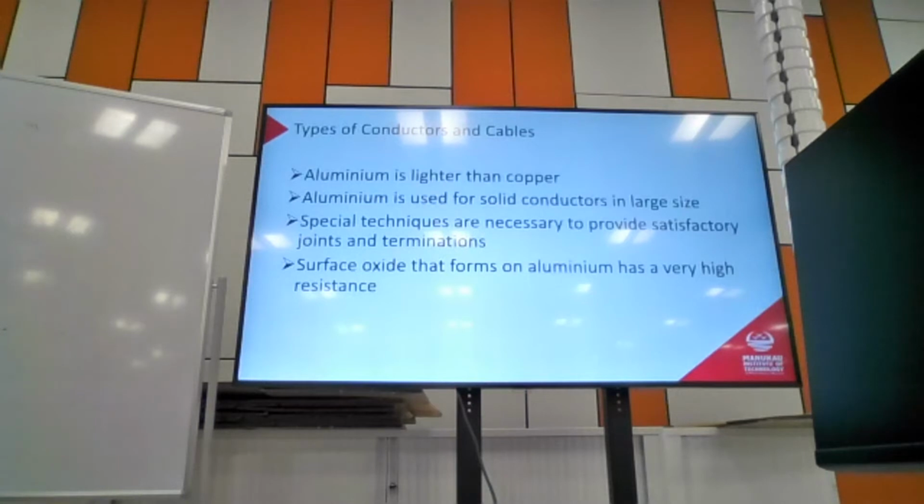Do I just use ordinary lugs? And he goes, do you have the aluminium joining kit? I was like, what? He said, you need a kit. I was like, where do I get one? He said, oh, well, we have one here. You can borrow it. And then he actually had all the instructions, and he talked me through it. You've got to sand the thing first, then you put the chemical on, and then they have this special compression tool and a whole bunch of stuff.